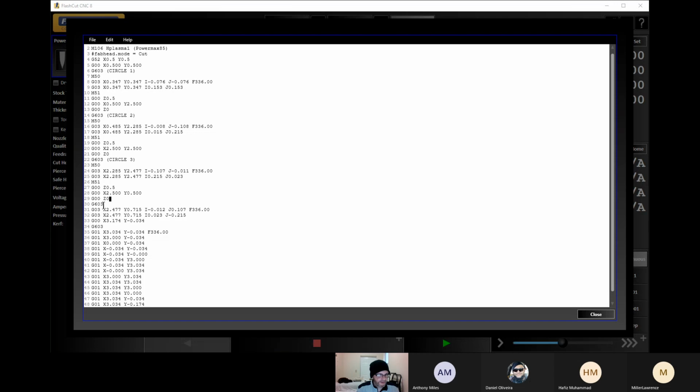All right, line 30. This is going to be our last circle. We'll call it circle 4. Exact same pattern. A lot of this is just pattern recognition. We know we have a G603. Very next line, turn on the torch.